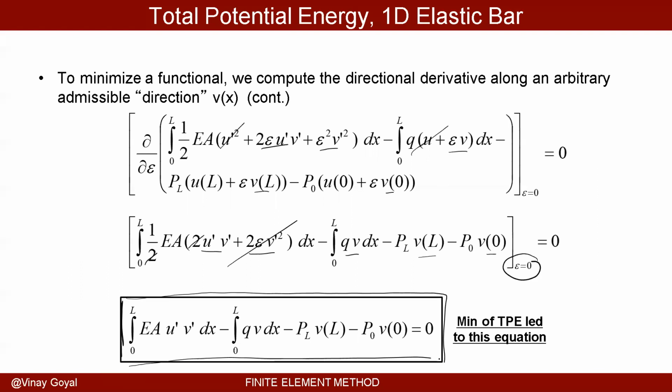Now there's something interesting when I look at this. I want you to go back to the weak form of the problem when I had the elastic bar problem. You're going to see from last week's lecture that the weak form actually matches this equation you see right there, which is a mathematical miracle. Why? Because when I developed the weak form, I started from the governing equation for an elastic bar, and I got the exact same thing you see on the screen.